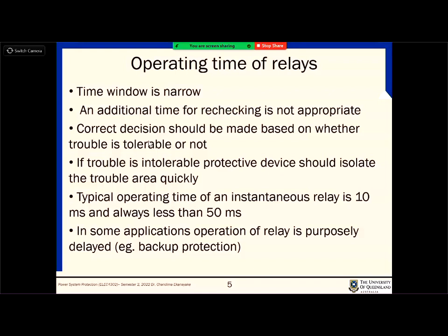So if you are looking at these relays, then you can also change the operating times within some settings. The same relay can operate, let's say, if an overcurrent of 50 amps is defined as overcurrent, the same relay can operate in 1 second or 2 seconds. You can set it, right? Those are the time settings of these sort of relays.